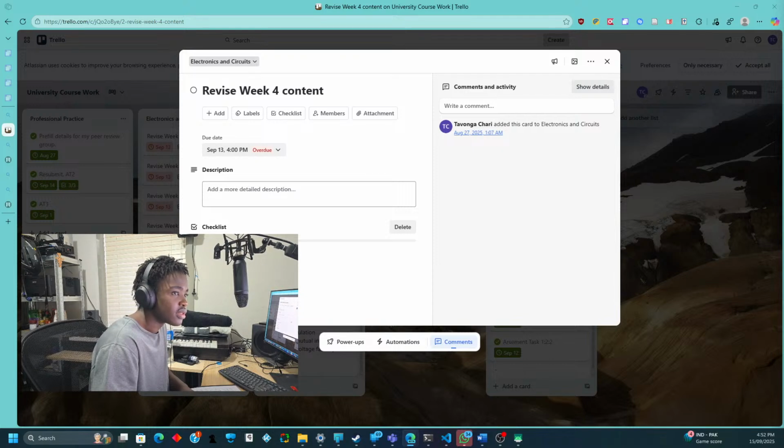So it doesn't go through there because the top is a higher voltage, right? So they're saying it goes to 10, and this one does not conduct. So it goes from 10 volts to 5, and then from 5 it goes to here, skips this resistor to 15. So that's what they're saying.